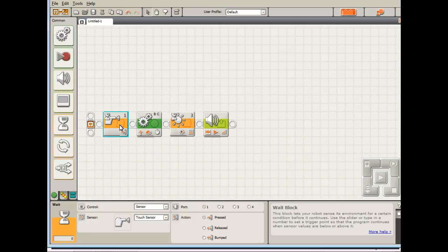So what's offline programming? Not online. I'll do it over here. No, offline. I'll do it right here. Yeah, this is what I'm doing right now. I'm doing offline programming. It's not connected to the internet. Well, it could be connected. Offline means we program away from the robot, and then we upload the program into it once it's been developed. Online means you're programming at the robot.